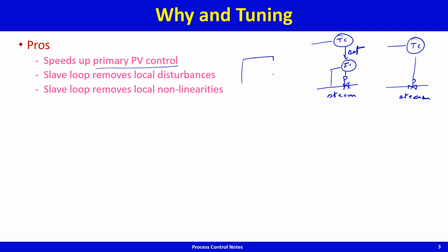So if I plot steam flow versus valve position, valve opening, this is from 0 to 100%, and the flow, I guess, will also go from 0 to 100%. Typically the characteristic of this is called the valve characteristic. The valve characteristic ideally should be linear, but more often than not it's quick opening.